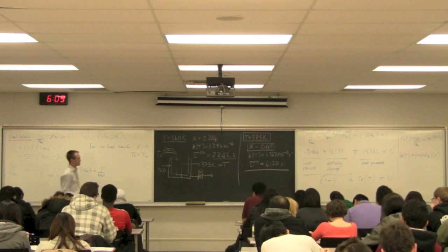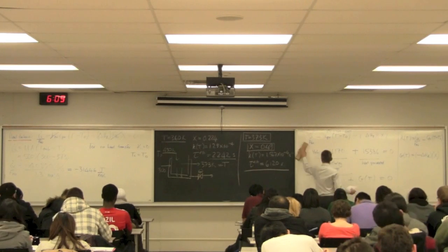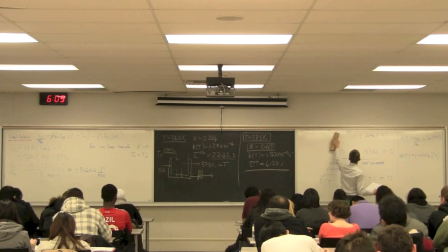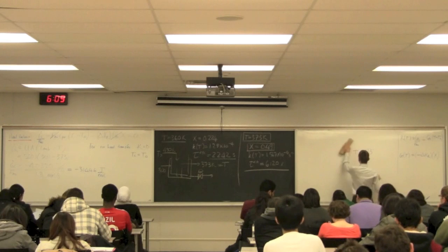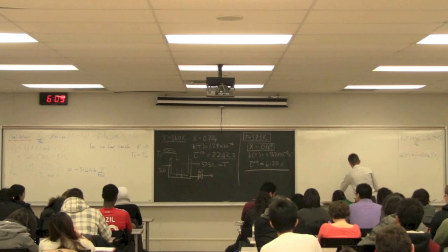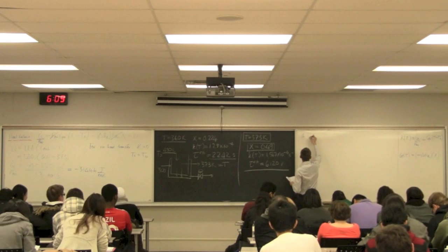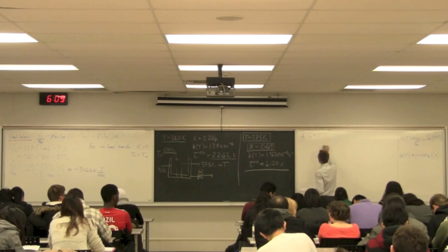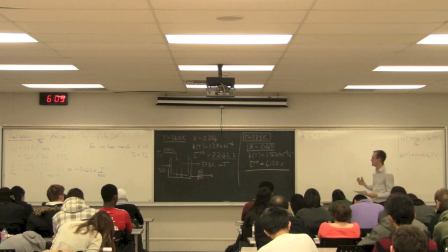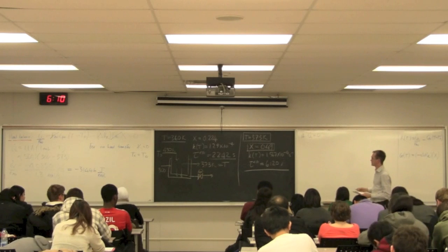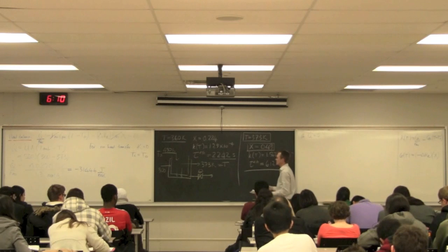And then what you can do is solve the system of equations that's out there and find what happens to conversion and what temperature you get. So let's just write that out quick. What you'll find is, take that heat balance equation. If Q dot is equal to 0, in other words, you're doing a risk analysis to understand what will happen in your process when an operator mistakenly closes this valve or it gets plugged in some way.